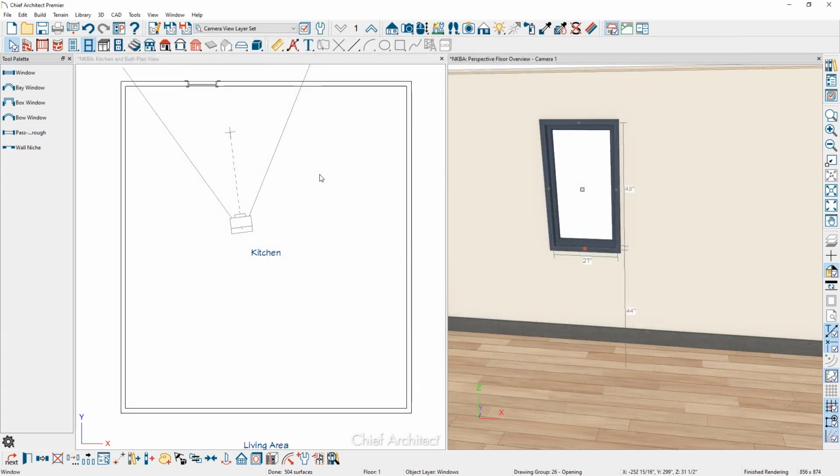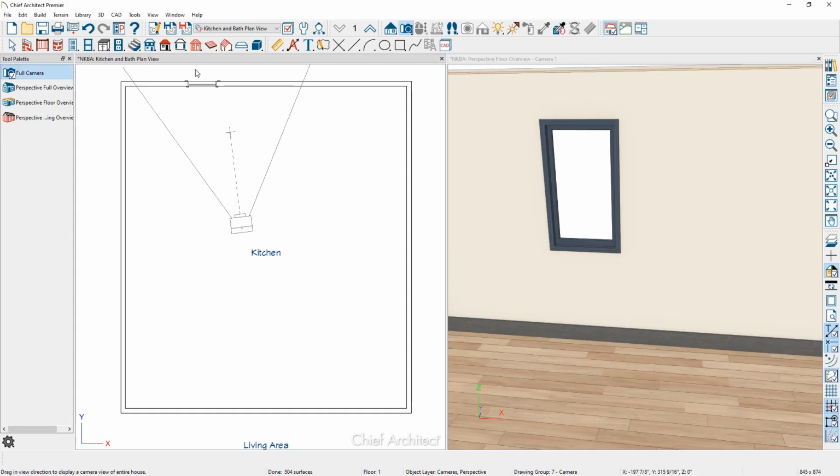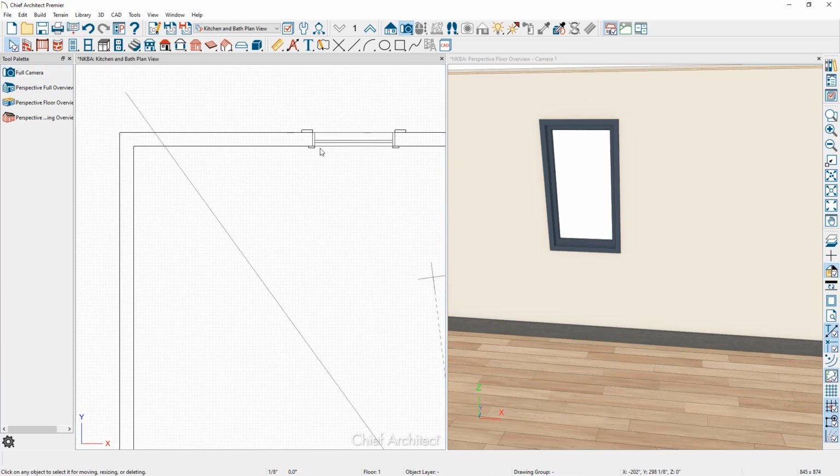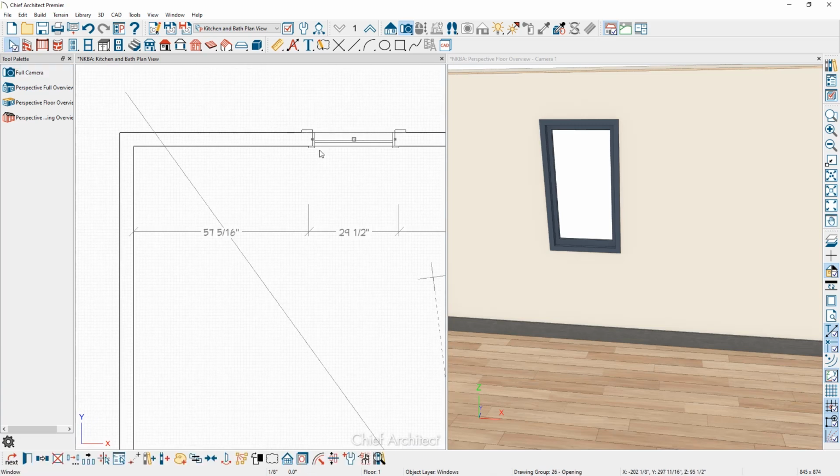And next, if we look at our floor plan view, you can see how the program added the window into this back wall. And if we zoom in and focus on this window and click once on it, you can see how the program produces a dimension going from the wall surface to the window casing, and the dimension is formatted in inches. The dimensions are picking up wall surface, opening casings, and are formatted in inches because the program comes with a kitchen and bath design template specifically with those settings pre-configured.